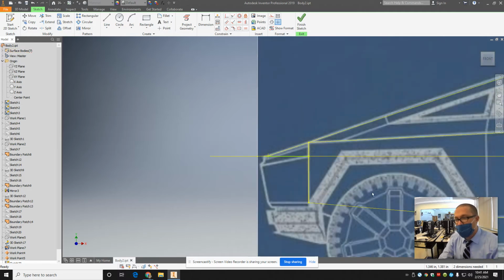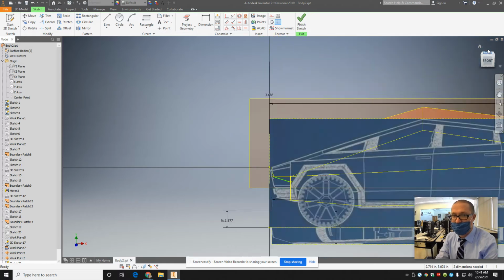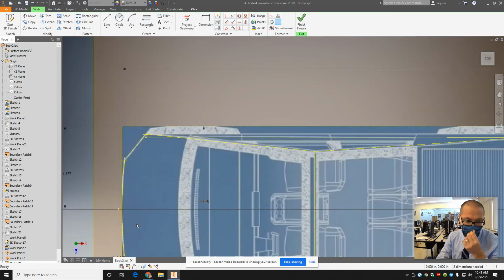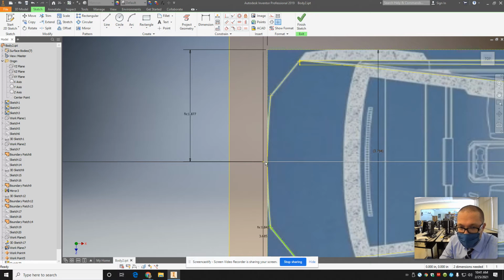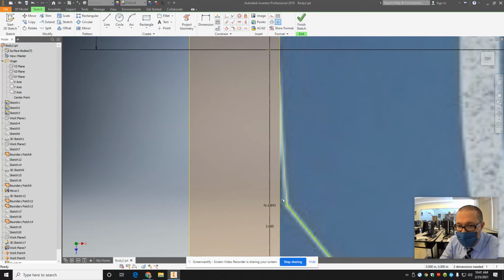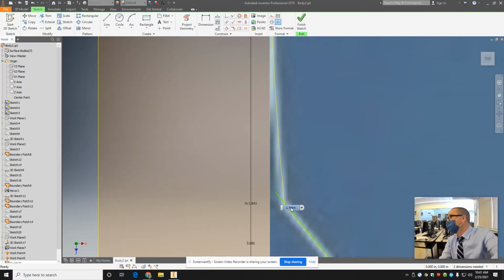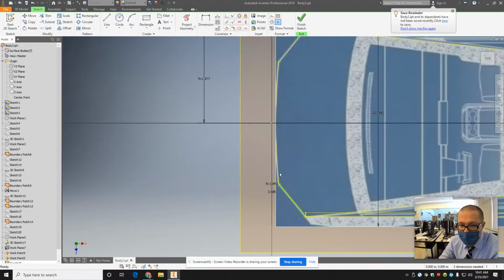What you can do, you can make a sketch on this plane and put a work point there and project it into this drawing we're in right now. I'm just going to split the difference between the arch and the front of this drawing here. So when I go back to this view, my arc I'm going to make go about halfway up here. And I'll show you that in a second. So this line you need to extend farther than the surface above it a bit.